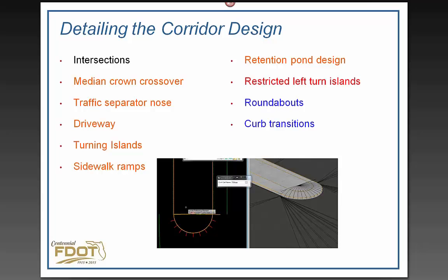And then I also want to go into some of the other civil cells that we've built for this particular data set, and that is an urban driveway, a rural driveway. We've also worked in the actual exercises, turning island and modeling out the island at the intersection of 98 and State Road 61 in our project data set. And I'll show you how that can be built by hand, and then also show you how you could create a civil cell from what we just built.